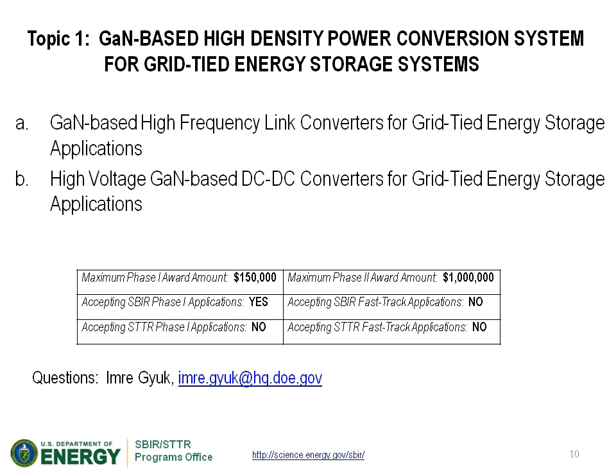Now, wide bandgap devices such as silicon carbide and gallium nitride have been very attractive. They have the higher switching frequencies, higher blocking voltages, lower switching losses, and higher junction temperatures. Higher switching frequencies means that we can have lower or smaller passive devices providing for high density design and also better bandwidth in the controls. Higher blocking voltages require less voltages utilized for high voltage applications, thus smaller designs.